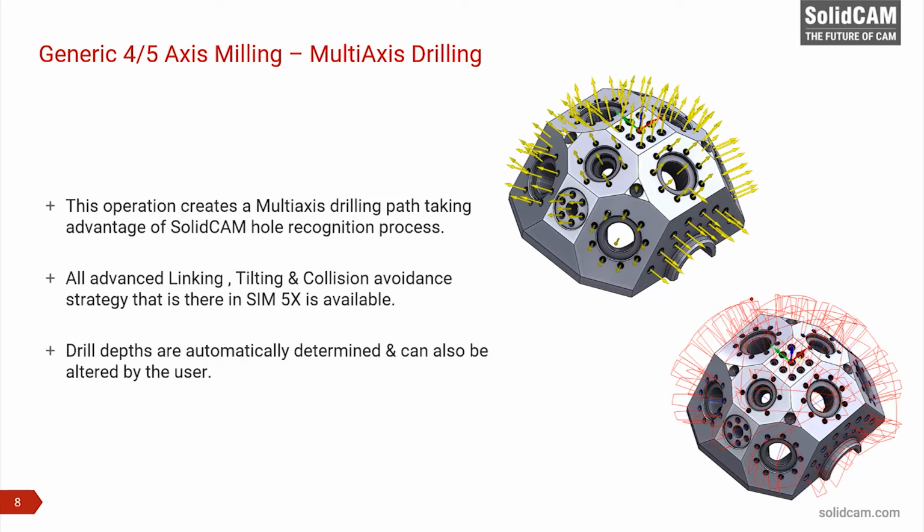For example, if the user just wants to do a center drilling, in that case he need not go all the way up to the hole depth. He can just say, I would like to go 1 millimeter for each of these holes. So SolidCAM will identify each of the holes and just provide 1 millimeter depth into each of the holes. So the depth can be altered by the user.